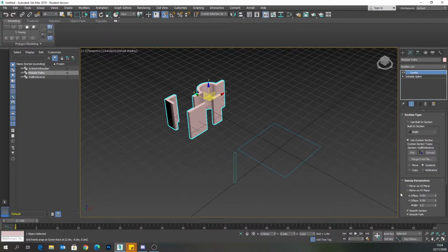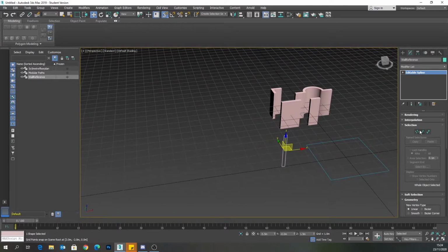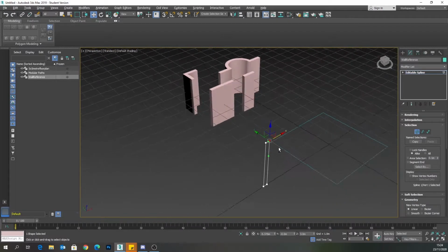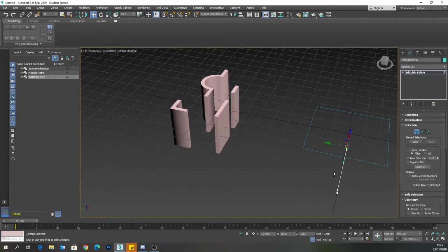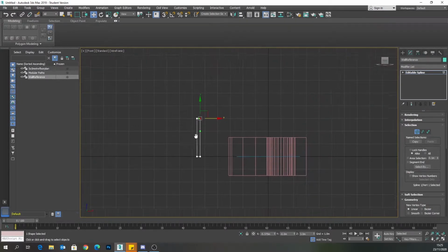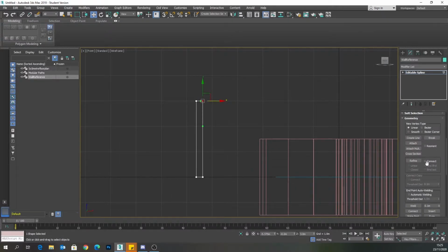Now, if you do get some issues with this, you might want to go to alignment in the sweep parameters and edit those so that potentially it's the bottom right-hand corner of the sweep from the 9 settings available, or mess around with the mirroring. Now, sometimes you'll get them acting a bit different. You can see the changes on the walls go on the inside, but actually the bay window does it on the outside. So what I'm going to do is just put a separate sweep modifier on the bay window as opposed to everything else, and I'm going to do this by separating the two objects.